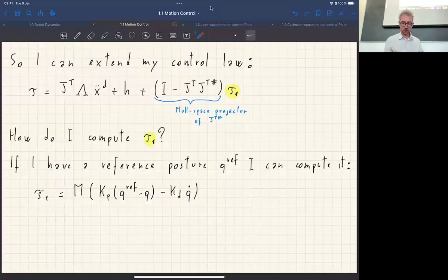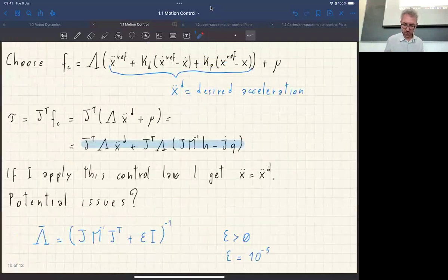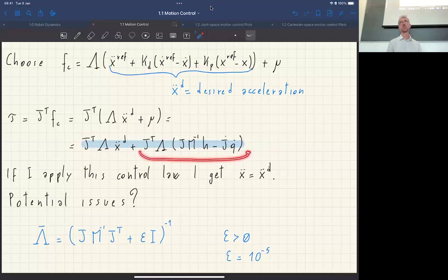So let's go back now to where we were before, which was here. We derived the first controller working in Cartesian space, which is based on the operational space dynamics. And that controller is the following one. Most of the complexity of this controller comes from this second term, because it contains many terms which are a bit convoluted to compute, especially this J dot q dot. It's a bit nasty to compute.